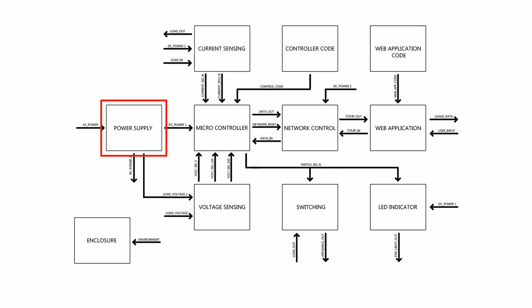The power supply is responsible for turning the 120 volt AC voltage from the utility into two different DC rails. A 5 volt rail and a 3.3 volt rail provide approximately 2.5 watts of power combined.